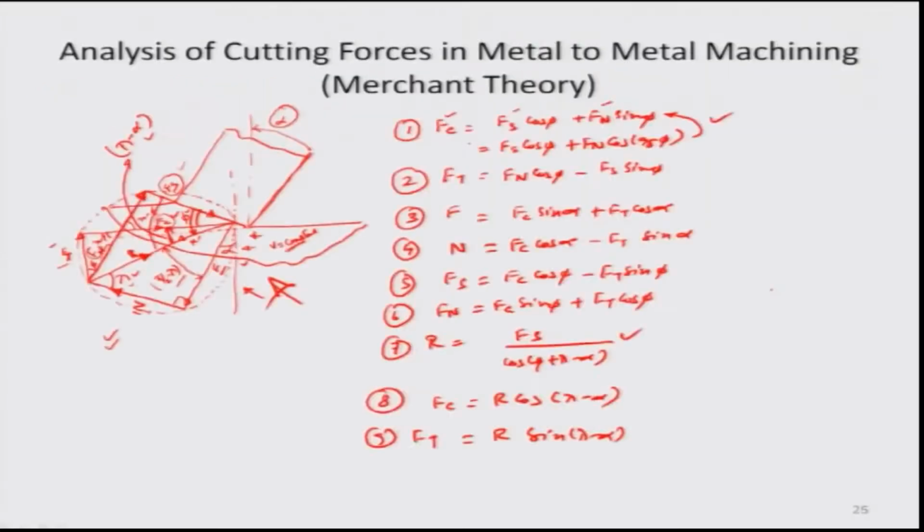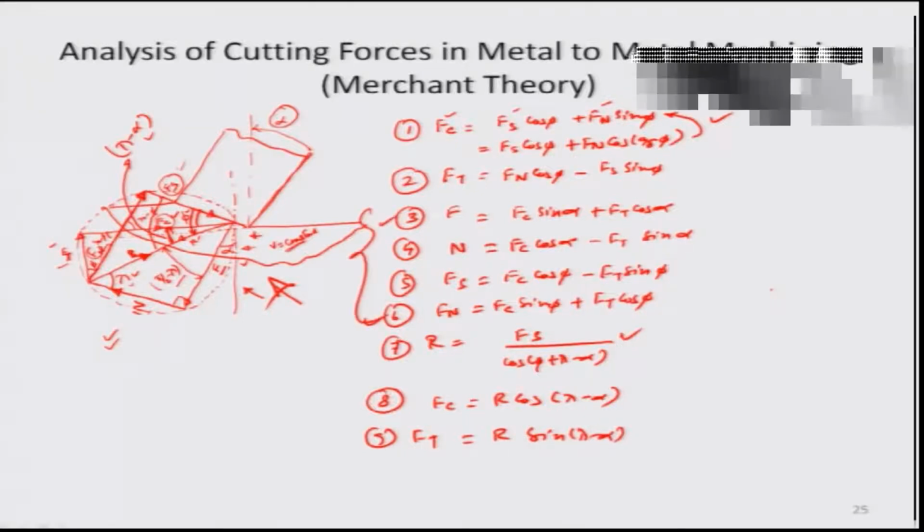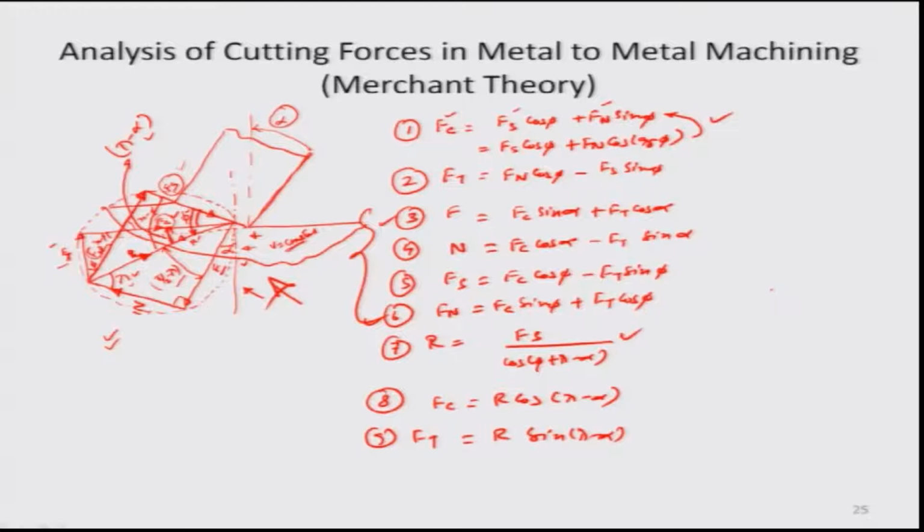You can see this equation 3 to equation 6, and so these are all the relationships between the various cutting forces and the tangential forces with respect to the angles that they formulate in the direction of the friction force, direction of the normal reaction, of the shear force and of the normal force along the shear plane.